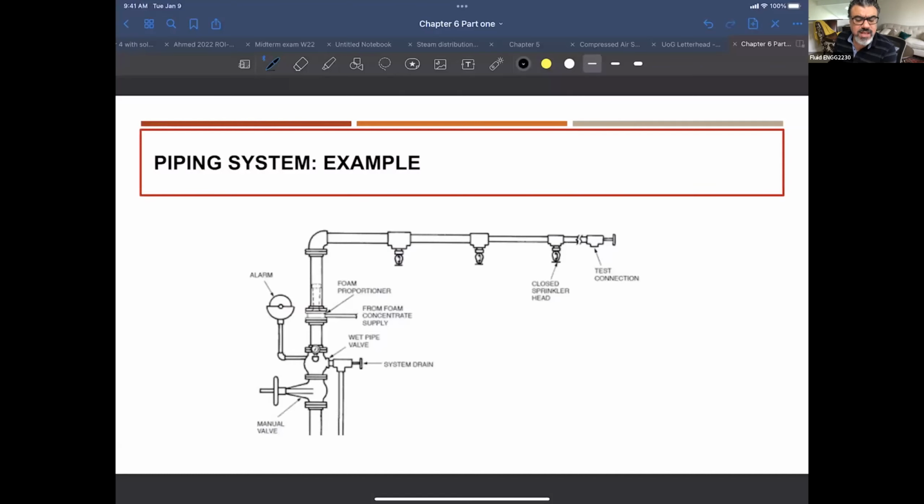It might have different diameters connected together with elbows, reducers or expansions, right? As you go inside this piping, this looks to me like a firefighting system. You can see here the sprinkler heads, right? You will see the piping contains a manual valve, some connections, elbows, and connections for these nozzles and so on.